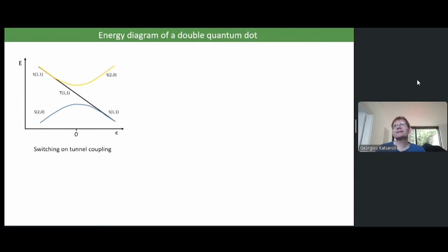That's something to be seen, as the phase space is very gigantic. But in general, I don't see any way around using AI for hole spin qubits: teaching an algorithm, asking for a delta g of this value and this tunnel coupling, and then the machine tries to tune up your device rather than a student, because that becomes really routine and tedious work.